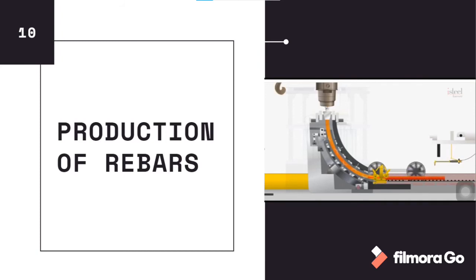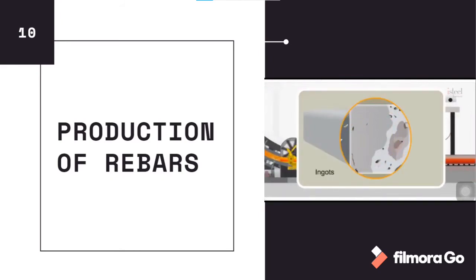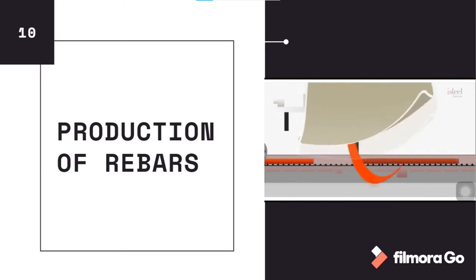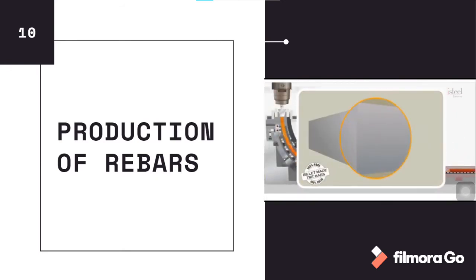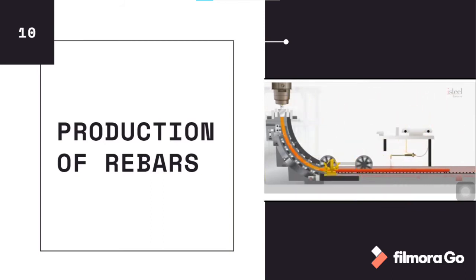A simple example to explain this. Steel cast from ingots has an inherent defect of piping. Look carefully and you will see that there is air trapped in the steel, which weakens the TMT bars. And in comparison, take a look at a billet, which is continuously cast and therefore there is no question of air trapped inside. It is therefore smart to insist on buying TMT bars that are made from billets.